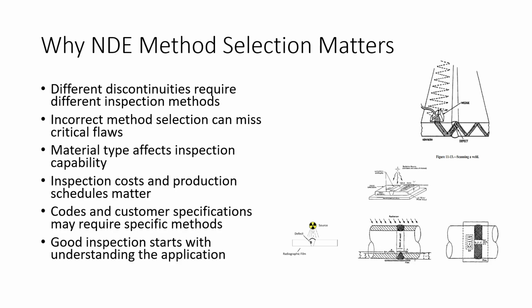And when I say fry, I mean expose them to radiation that they probably shouldn't be exposed to. Or we have to shut down an area so that we can take those shots on certain pieces of pipe. So when we start with non-destructive testing, we have to understand that the inspection starts with understanding the base application of what it is we're doing.